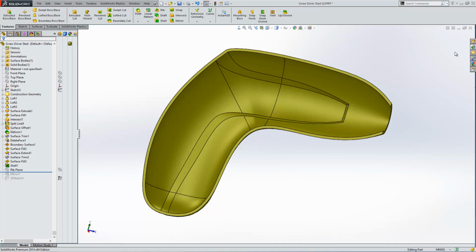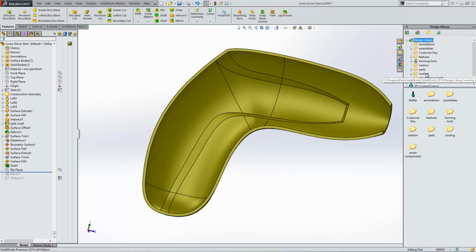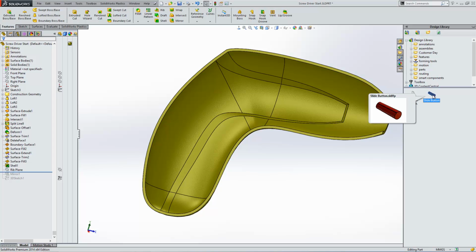To bring this item into SolidWorks, I've actually already got it saved within the design library. Now, if you've not used the design library before, you can go into here and bring in existing features that you might have already created and drop them into your model. You'll see I've already created a folder in here and I've saved this item, which is simply just a little extrude feature. But to save you from creating this feature over and over again, I can drop this into a number of models and reference to it quite easily.